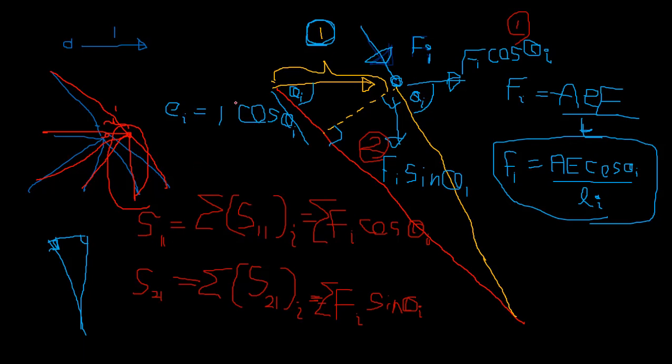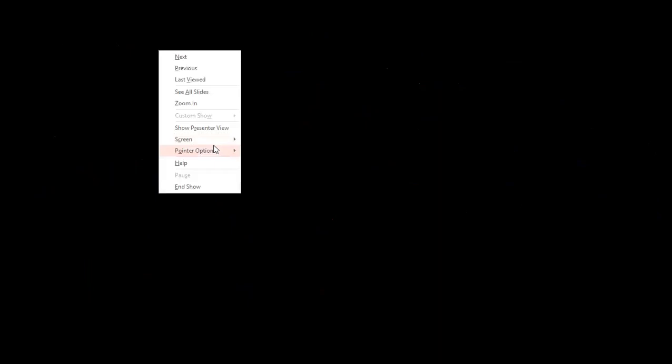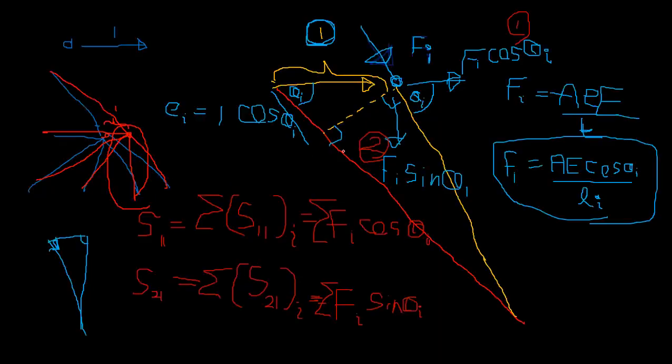Similarly, this is the second step, right? You can see now you find the stiffness coefficients for every member, considering a representative ith member, and you find the force, that is the action, for a unit action in each member.